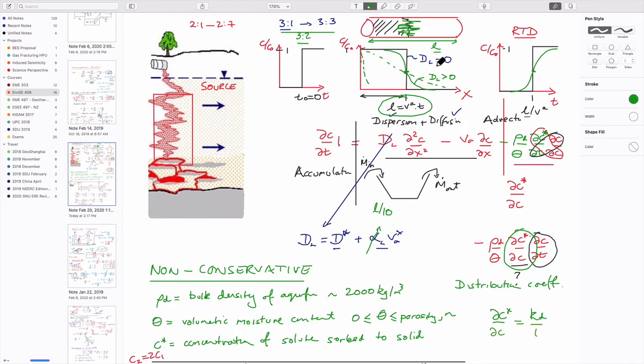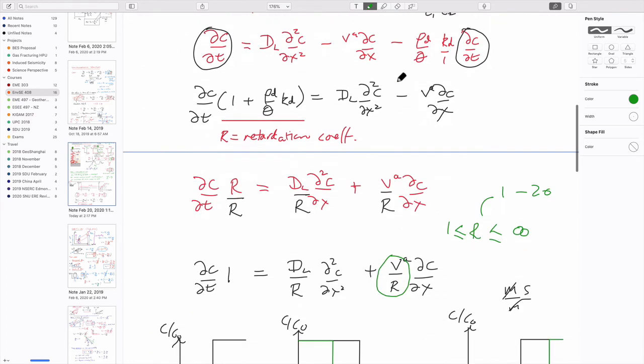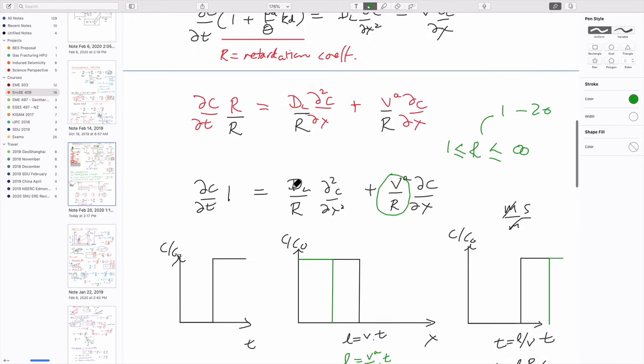And so a small magnitude of dispersion coefficient gives us a very sharp front. If we are dividing the true dispersion coefficient by a number bigger than 1, it's going to be smaller, and so effectively it would sharpen the front. So not only would it take longer to get downstream, but the front as it goes through would tend to be sharper.